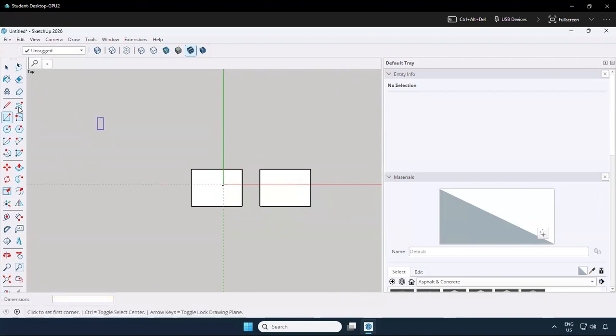You might also notice that the line, as I drag it across, is a red line, which is running parallel to the x-axis, and then it turns green when it's on the green axis or the y-axis. For anything else, that line color changes to black. This is to denote whether things are running parallel or perpendicular.